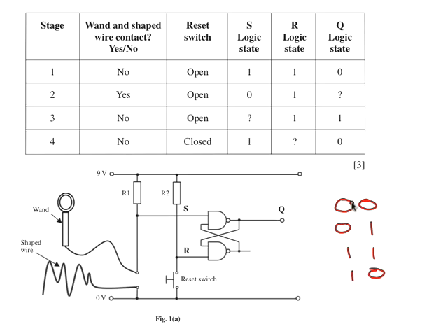So an AND would give us a 0 for 0 and 0, so this must be a 1 for a NAND. 0 and 1 for an AND gives us a 0, so a 1 for a NAND. A 1 and a 1 for an AND gives a 1, and the opposite of that, remember, must give us a 0. And a 1 and a 0 for an AND gives a 0, so for a NAND, that's a 1. So 1 everywhere, apart from when it's 1 and a 1.